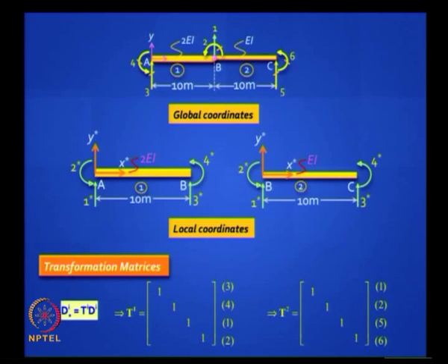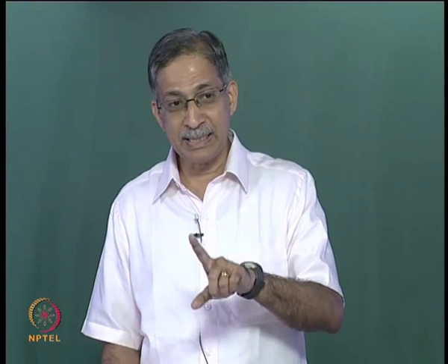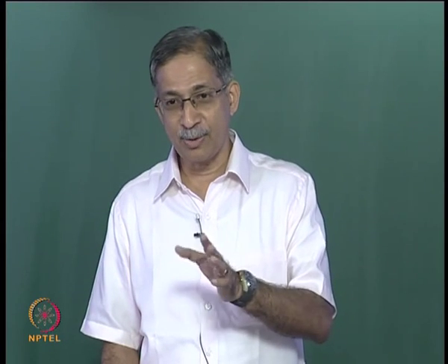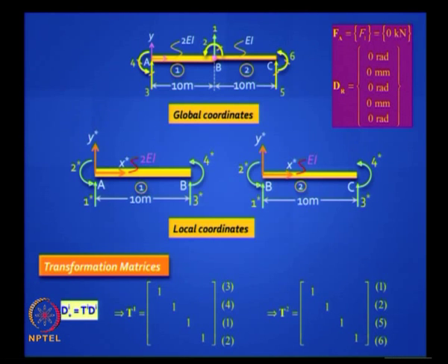So you have only one active degree of freedom, and in the input data you do not have any direct loads, because that 30 kilonewton meter is not going to the global coordinate, it is going to the member end, and there is no support settlement. Is it clear? So your input data is this. So far it is clear. Next,